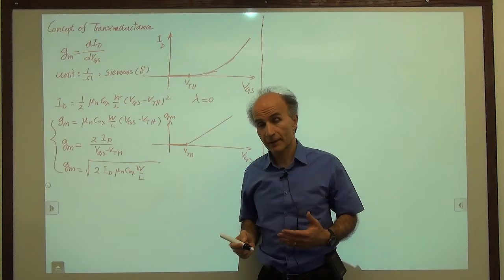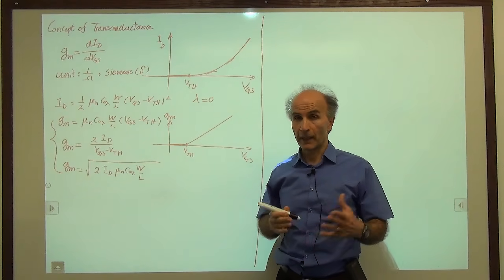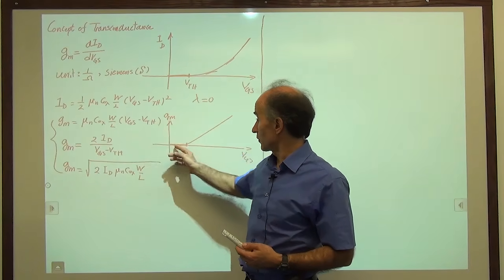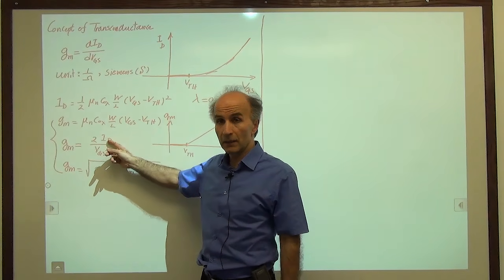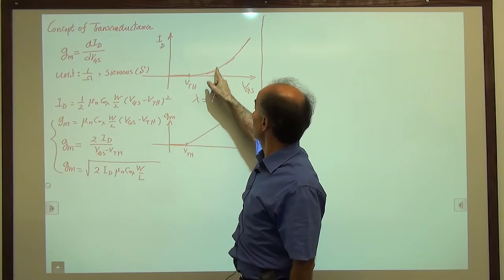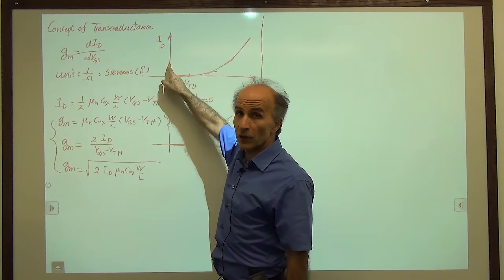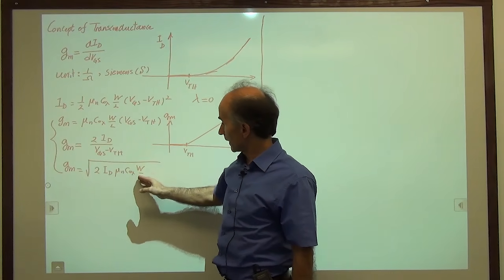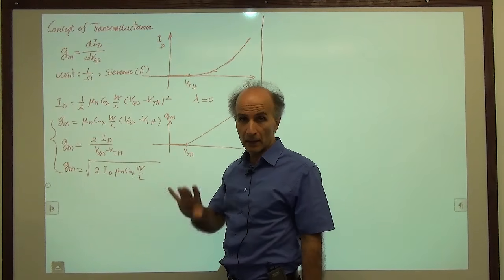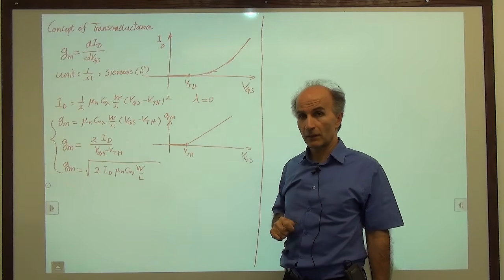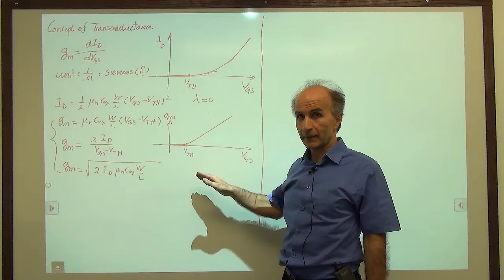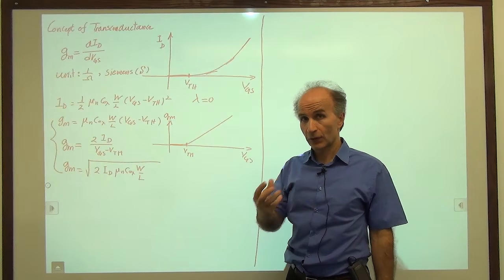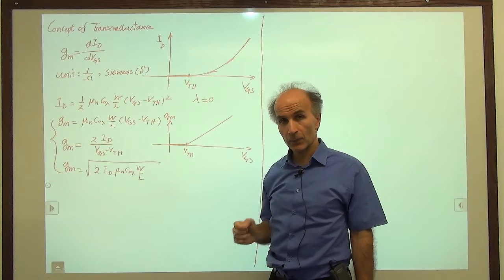And it's very interesting because each of these equations tells us something about how GM varies with various parameters. GM varies with VGS minus VTH, yes. GM varies with ID, yeah, we saw that, right? We saw if we have biasing here, we have a lower GM than if we are biasing here. And GM also varies with W over L, as indicated here and here, and also some interesting things. So these are things that we have to study in the future. But the transconductance of a MOS device, which tells us how strong the device is in converting a voltage to a current, has these three expressions for it.